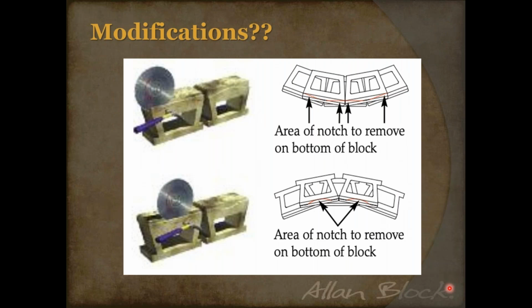When you do these really tight radiuses with your full size block, you got to remember these are 18 inches in length, and you're trying to do a 4-foot radius. You're going to see that the blocks kind of have touch points to them. They're going to be hitting the blocks below it, for example, here and here, and that's going to force the block back where it could actually expose the top of the course below it, and so you can see that lip. Aesthetically, that's the problem. Structurally, there's no issue with it. So this is an aesthetic fix that you can make, and it's outlined in our commercial install manual as well.